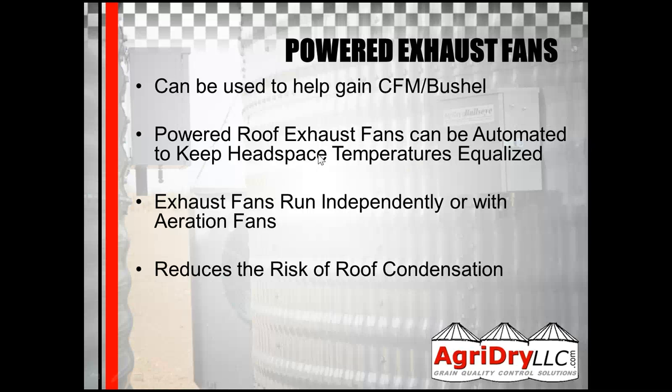The great thing about it is we can actually automate those into our controller, so we can automate them to read the headspace temperature and then run them individually by themselves, without running the bottom fans, just to keep the headspace cool. That helps so you don't have condensation and drip throughout the spring and summer, where the grain cools down, it's hot outside, and the headspace temperature warms up tremendously. We can just run those roof exhausters automatically from our controller by reading the temperature at the headspace and the grain temperatures, and then help keep that headspace cooled down. So it works really well with our controller, with a separate program that we have for that.